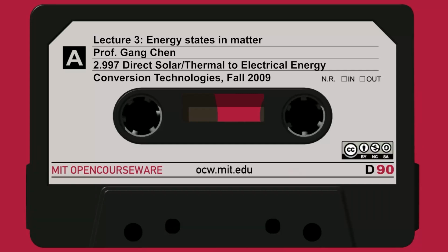So let me again start with this figure of merit ZT. I said that when you do thermoelectrics, when you say I work on thermoelectrics, often people ask you, what's your ZT? That shows you know something about it. And it has three parameters: the electrical conductivity, the Seebeck coefficient, and the thermal conductivity. And the thermal conductivity, the heat conduction in the material, consists of two parts.